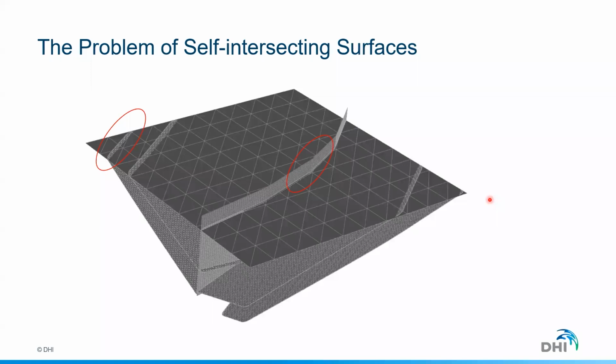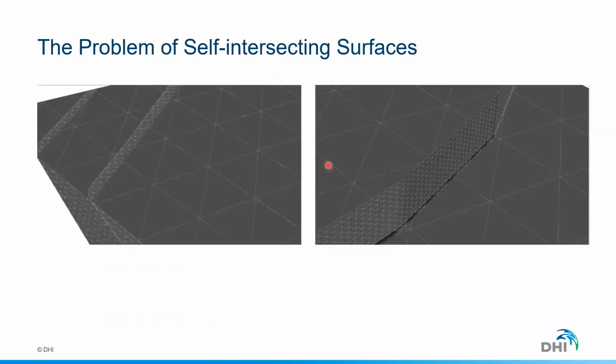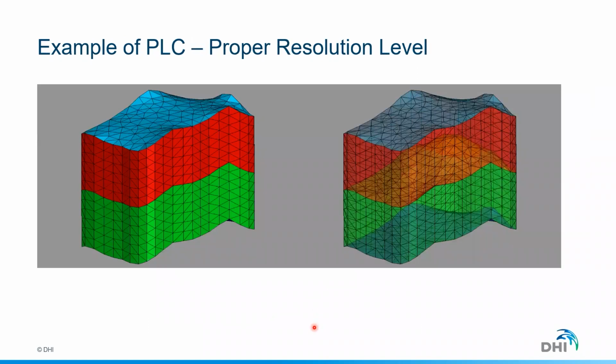So how does self-intersection happen? From my experience, it comes because these geological software packages triangulate some part of the information in one way and the other part differently. They might triangulate the horizons and the faults very, very finely, and obviously they do not fit. If you zoom in, you will see the triangulation is not fitting in these cases. These are simple examples where it fits. It's nice, but we know the geology is complex, so we want to achieve higher levels of complexity.